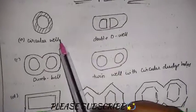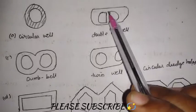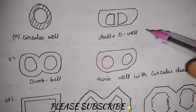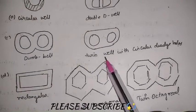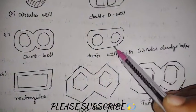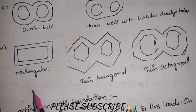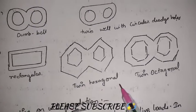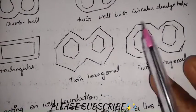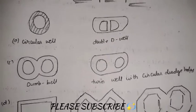Okay, so generally these are the shapes of well foundation that are accepted. First comes the circular well, the circular one with the hollow space in between, which is filled again with concrete. And this is a double D well. See, it has a D section on both sides, so we call it a double D well. It is a dumbbell type, and here we have a twin well with circular dredge holes. Here we do not have the dumbbell shape, we just have straight lines. So again, this is a twin well with circular dredge holes. I have explained these dredge holes in the definitions also. This is a rectangular one. This is twin hexagonal, having 6 sides. Octagonal, having 8 sides, and twin in combination. So these are the shapes generally adopted for the well foundation.